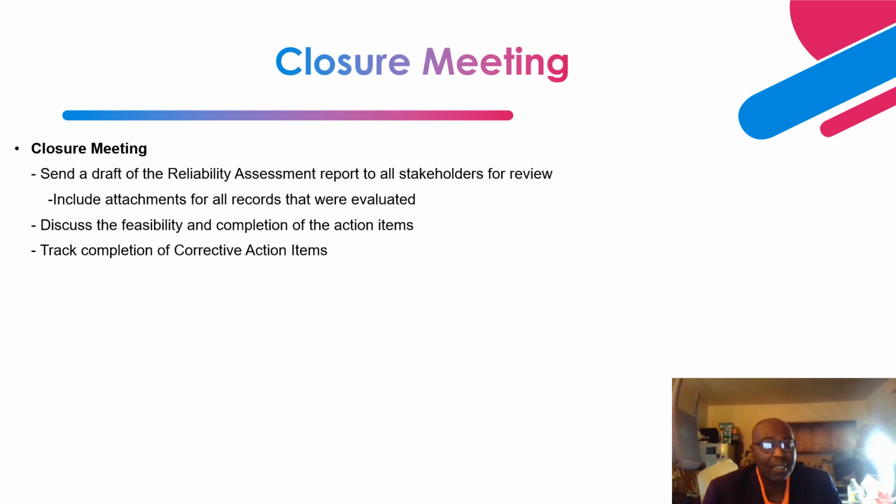You evaluate the current testing results against what the criteria is supposed to be. Next is testing of the capacitance of the main tank and the bushing, and the tan delta or the power factor.